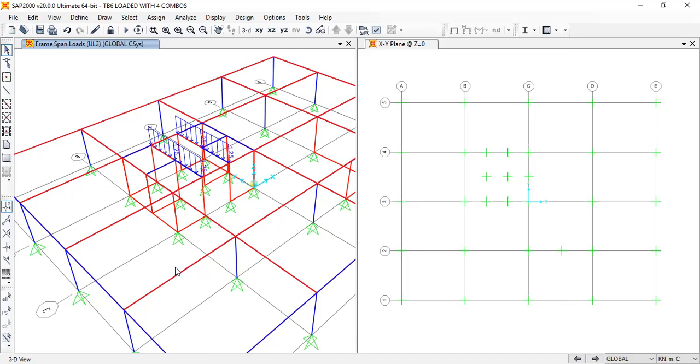So the interior panels are okay, right? Because this side also gets deflection, the other side also gets it, so the torsion will be mostly negligible. But here at the end, since this beam transfers a moment, this beam will have a torsion, so it's better to keep it as simply supported, right?